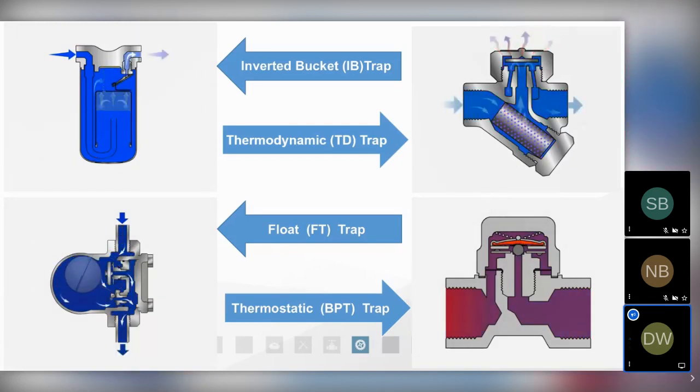We also need to allow for sizing the steam trap to allow for that increased mass of condensate that is going to be present when we're warming the system up, what we refer to as the warming up load, which is typically 2 times the mass that we experience for the running load, the normal operating conditions. So that's all well and good when we're considering the removal of the condensate on the plant steam side.